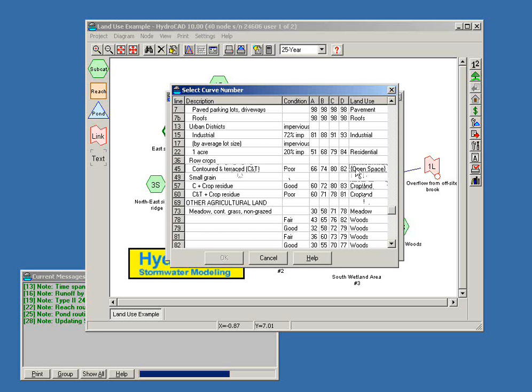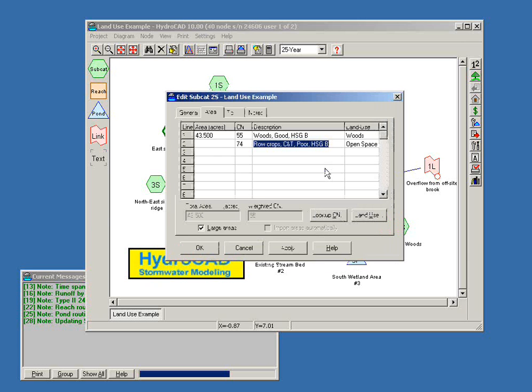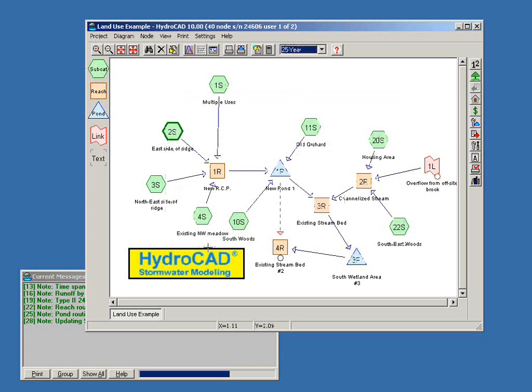And the curly braces appear here as a reminder to you that this is an override within this particular project, that it's not actually using the default settings straight from the ground cover lookup table. So we would select the line off this table and put in an area, and we've now picked a ground cover with a custom land use assignment. So that's the process of setting up the land uses and customizing the land uses.